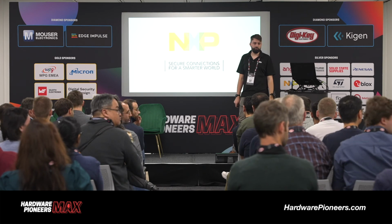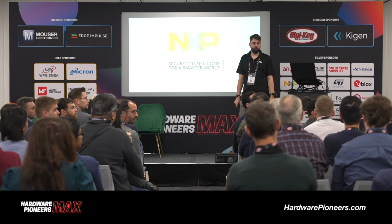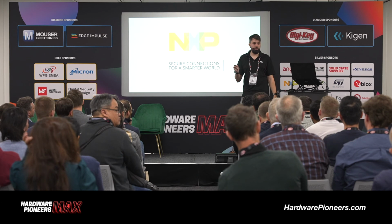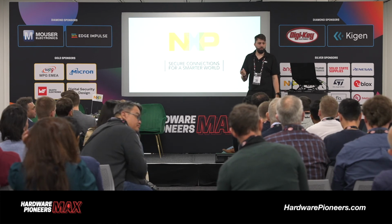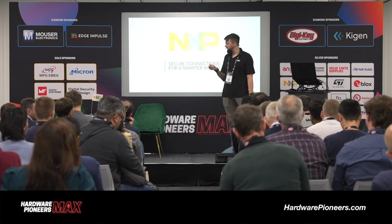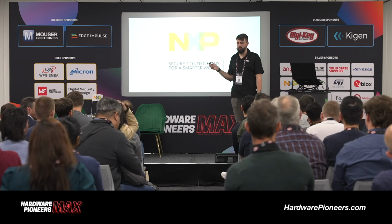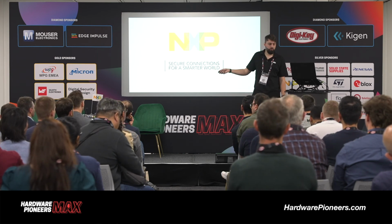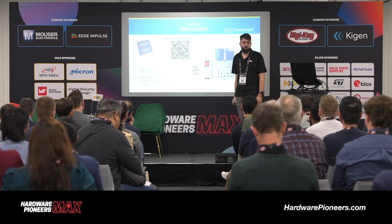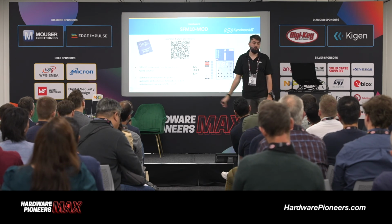Do you know how the NXP chips compare with the DW3000? It's mostly on accuracy. I think the DW3000 doesn't have a two antenna or multiple antenna solution yet. It's mostly on accuracy and usability. Also, this new chip is the first single chip ultra-wideband solution. It consumes a lot less power, and the documentation for it is much better.